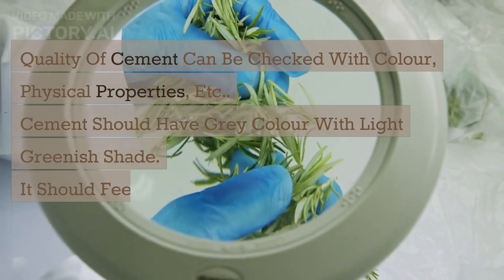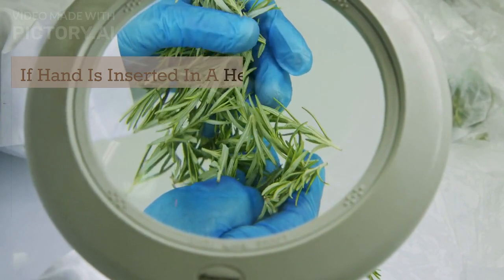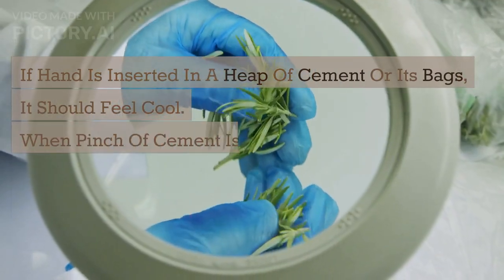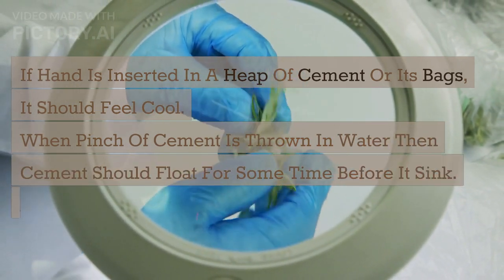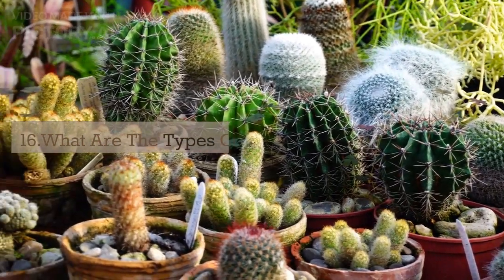It should feel smooth when rubbed between fingers. If a hand is inserted in a heap of cement or its bags, it should feel cool. When a pinch of cement is thrown in water, the cement should float for some time before it sinks. Also, it should be lump-free. 16. What are the types of cement?